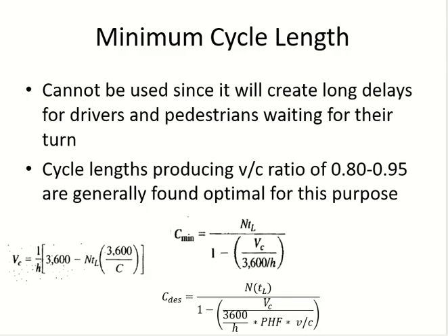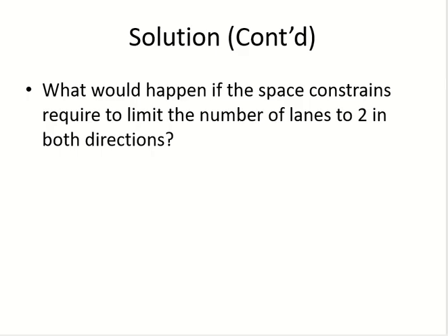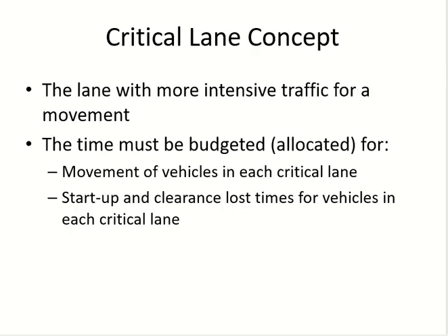Peak hour factor depends upon traffic trend, how they are going up and down, 15 minutes and whole hour and so on. You cannot change. We can change this. We can do something to change this. We can play around with the number of phases as well. This one again, driver behavior, lost time. Clear? So the other parameters which we can work around with, we can see what happens.